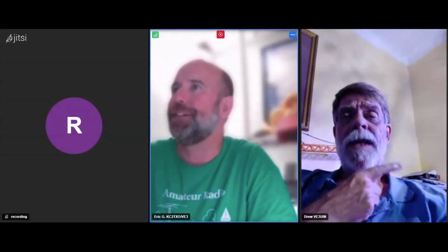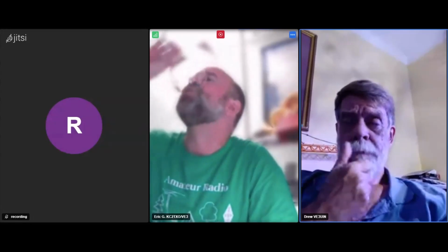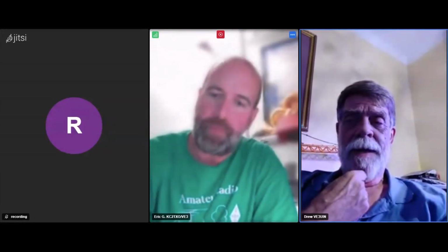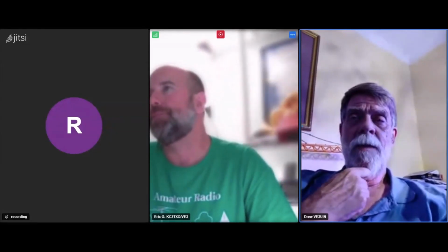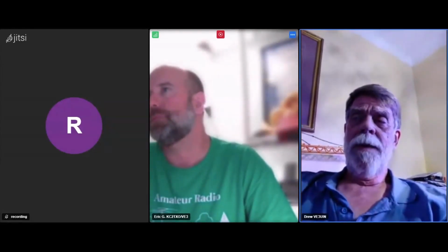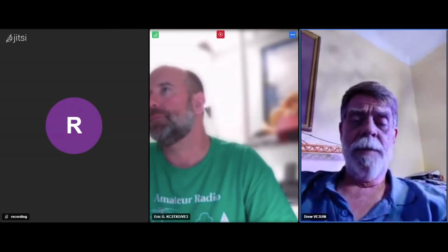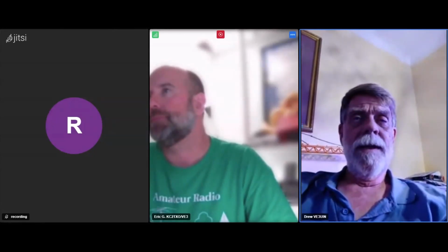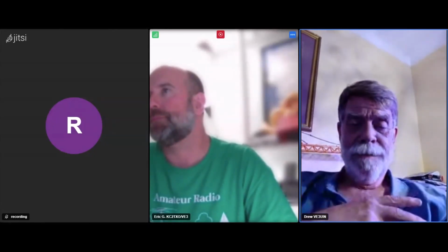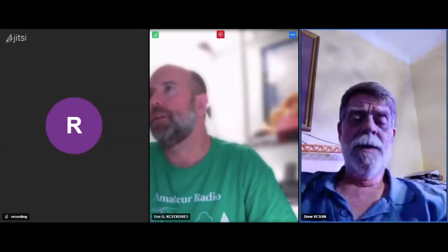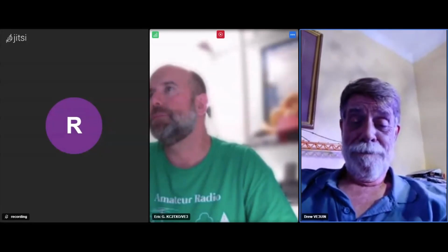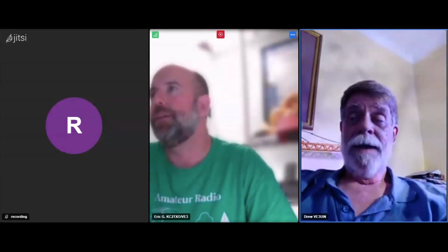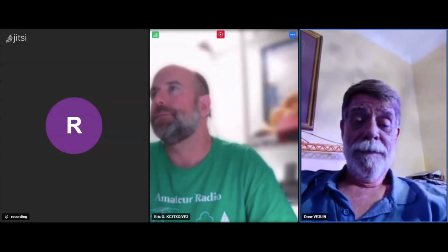Well, Peter's got a pretty good one. He's got an off-center fed, and that uses a 4-to-1. And there's two versions of it. One is 1/3, 2/3 with the balun at that point, and the other one, I think, is 1/4, 3/4. There are great schools of thought between the two, but I'm talking about a pretty simple setup. So I actually have a 4-to-1 I'm going to try.